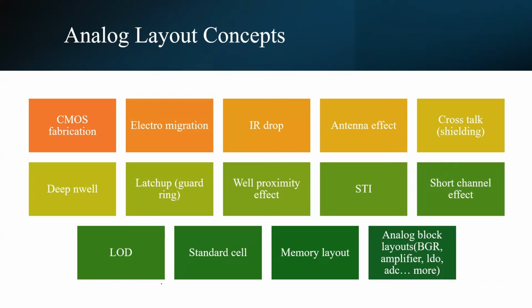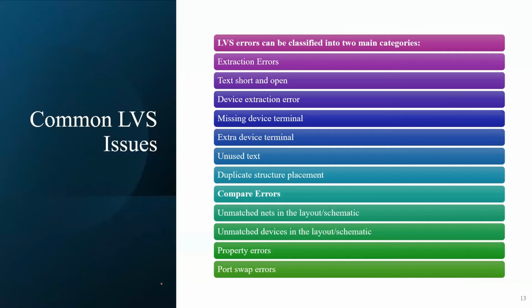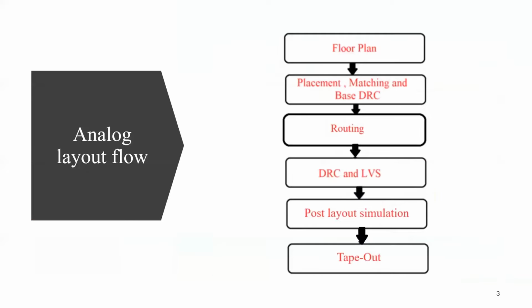That's the overall view of the analog layout, which we actually saw in this PPT: floor plan, placement based DRC, routing, DRC, LVS, post layout simulation, and tape out. This is the complete overview of the analog layout flow.